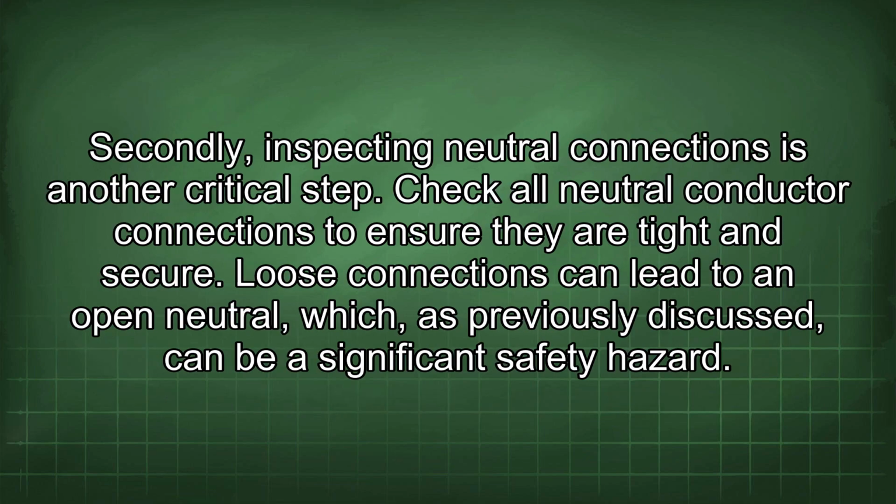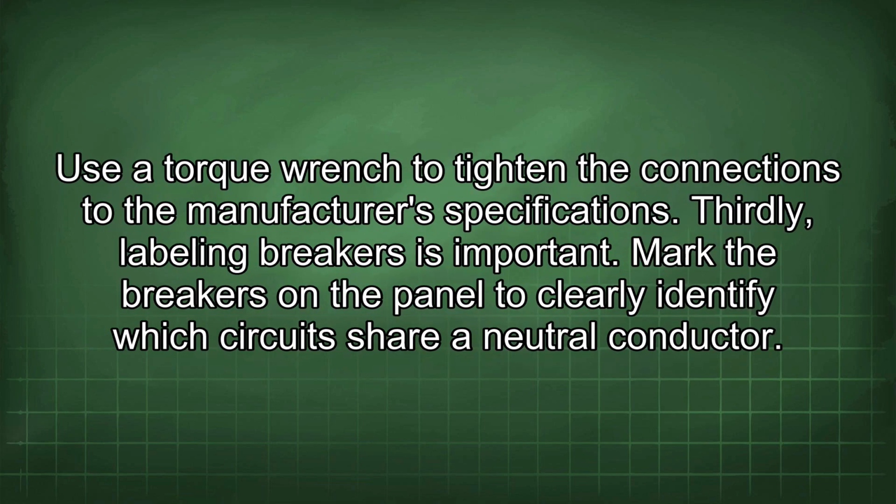Secondly, inspecting neutral connections is another critical step. Check all neutral conductor connections to ensure they are tight and secure. Loose connections can lead to an open neutral, which, as previously discussed, can be a significant safety hazard. Use a torque wrench to tighten the connections to the manufacturer's specifications.